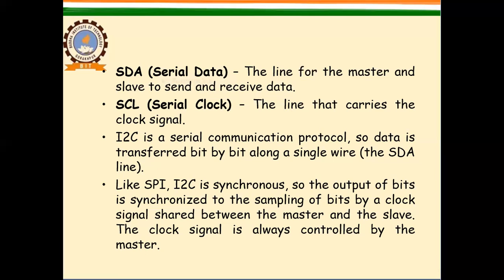SCL, serial clock, this line is used to carry the clock signal, which is used to synchronize the data transmission between these two. I2C is a serial communication protocol, so data is transmitted bit by bit along the serial wire SDA, one bit after another.